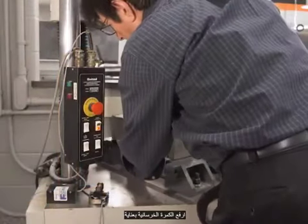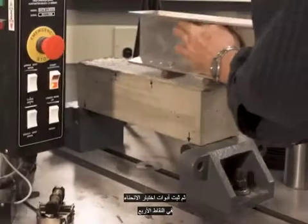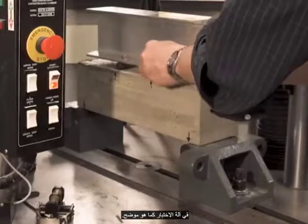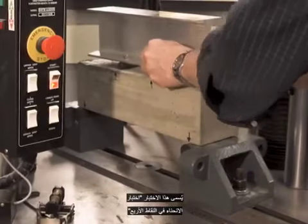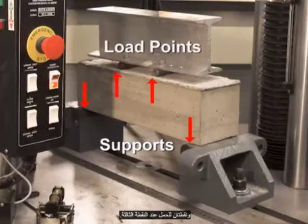Carefully lift the concrete beam and install it into the setup. Then install a 4-point bending test apparatus in the testing machine as shown. The test is called a 4-point bending test because we have 2 supports at the ends and 2 load points at the third point.